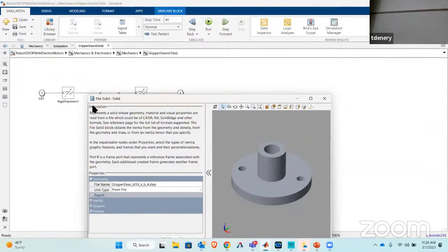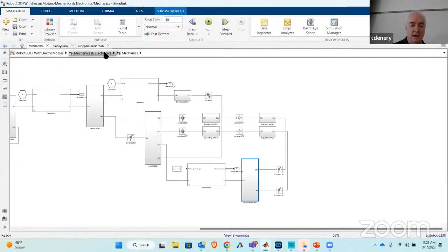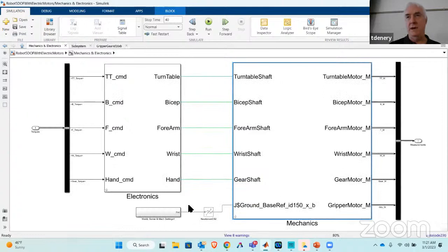All right. Now I kind of picked a boring piece. We could go into that animation. I could show you exactly where that piece is. But it's somewhat interesting because I'm seeing that it's connected to at least 3 things. And I won't dive too much more into that, but I'll just say we're doing mechanics. If you look closely, you might have even noticed that there's a place to assign the mass of that part. Of course, it's a geometry created from SolidWorks, and therefore, knowing its shape, you know its volume. If you know the material it's made of, you know what its mass is. You also know what its inertia tensor is.